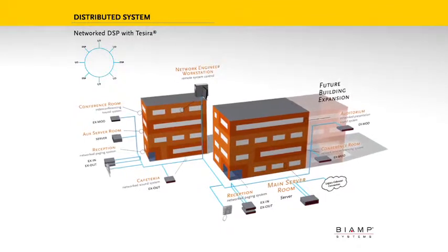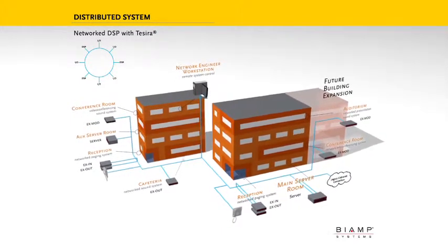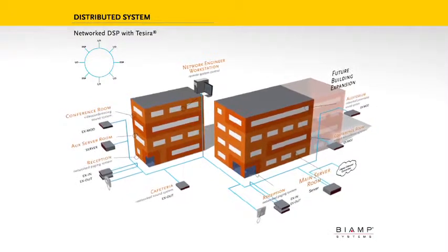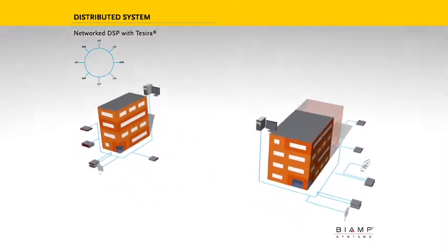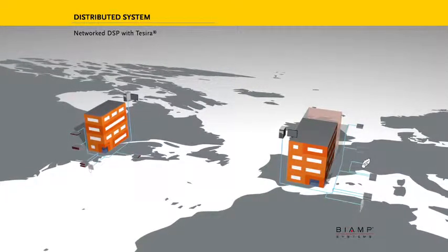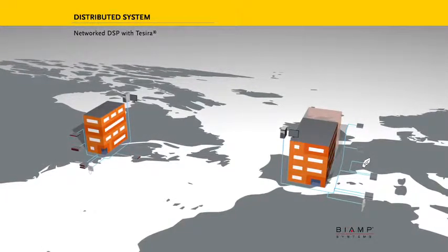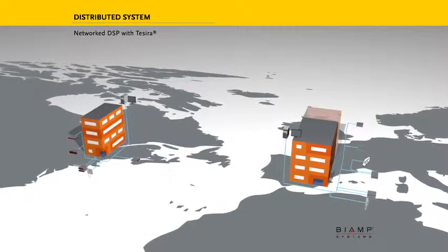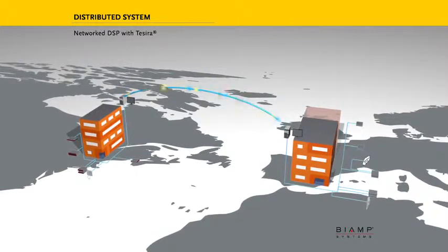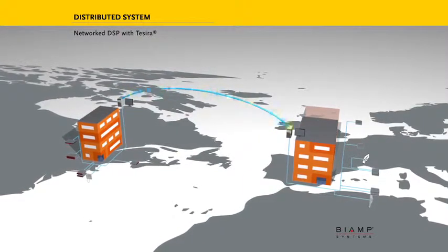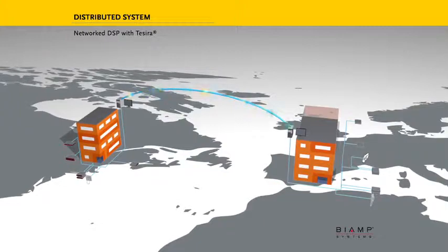A distributed configuration involves multiple physical locations of DSP placed closer to the I/O endpoints and is often utilized in instances where buildings are separated by large distances. In some cases, organizations may entirely prevent audio transport protocols from passing over their WAN connections. Centralized system control, however, can still be maintained via VPN connections.